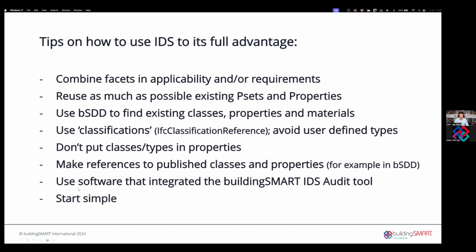But the most important tip of all: just start simple. IDS is very powerful with all of these different facets and combinations, but please just start very simple. We saw that 90% of the use cases is indeed just entities and properties. So please just start there and work your way up from there into these more advanced things as well.